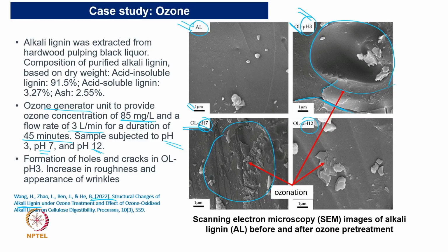You are able to find a number of debris, more cracks, or maybe a brittle fracture kind of thing. Even coming to the basic, alkali nature, we are able to find the faults or maybe surface damage. Of course, if I compare, the original surface, least damage will happen when the environment is alkali, or basic. Coming to neutral, there will be some damage, and then coming to acidic, there will be severe damage.